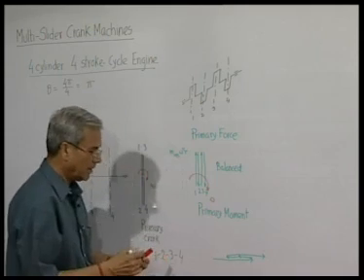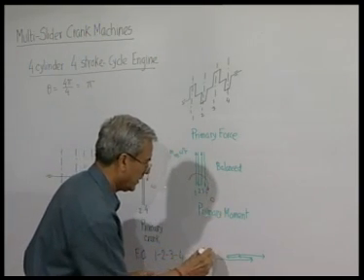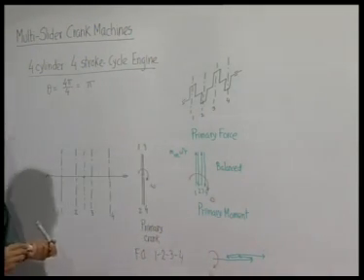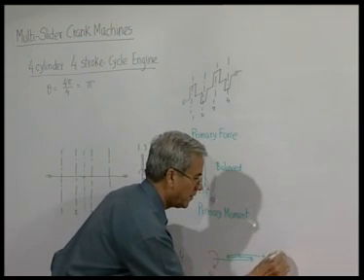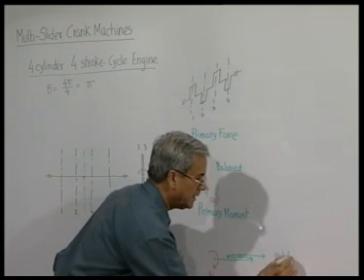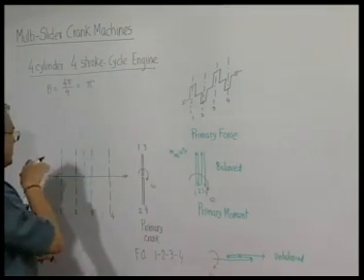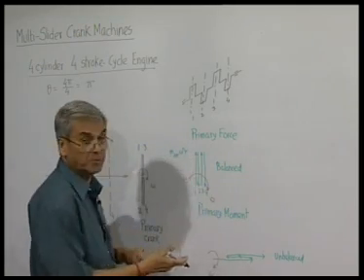So, the resultant moment, and the whole thing of course, is rotating. So, primary moment is unbalanced, very clear, and at any instant, since the forces are vertical, the moment will be in the horizontal direction, or in a direction perpendicular to the board.